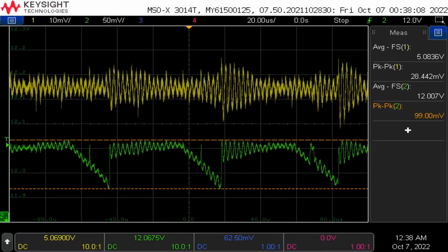This is a screen capture under the previous test conditions. It is clear from this picture that the linear regulator in yellow has stayed within 4.5 and 5.5 volts and has a less than 1% ripple. It is also clear that the power converter in green has output 12 volts and has a less than 1% voltage tolerance.